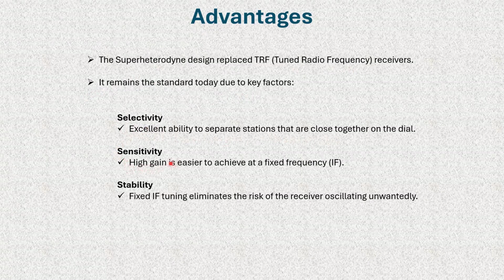Sensitivity, high gain is easier to achieve at a fixed frequency, which would be the IF here. And of course, the stability, the fixed IF, because that IF is fixed, eliminates the risk of the receiver oscillating unwantedly.